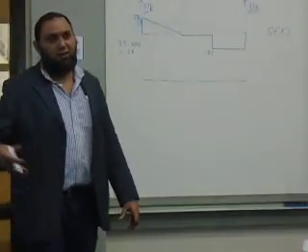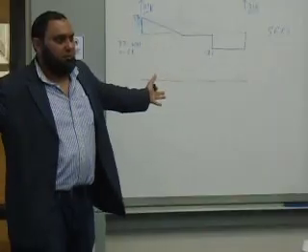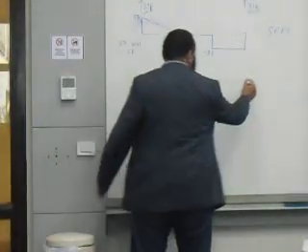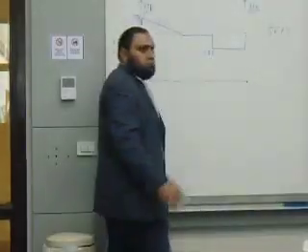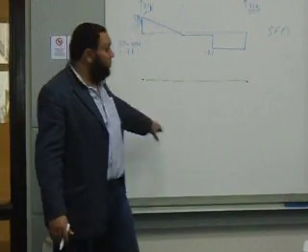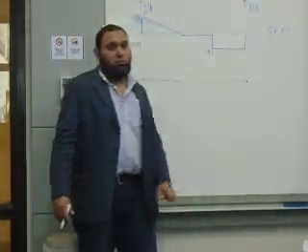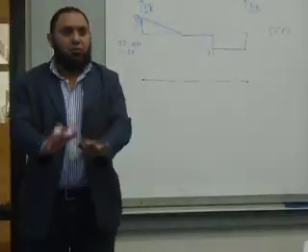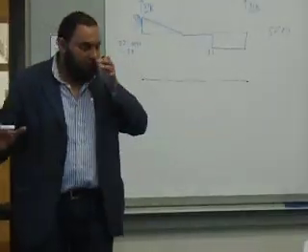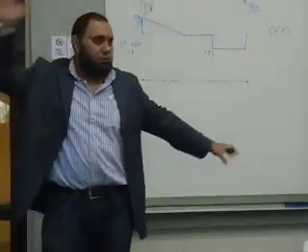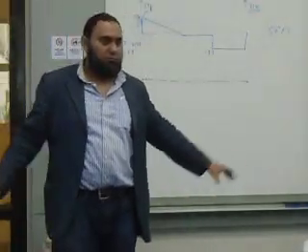And there is just air beside me, right? So these 2 points, I know that they are zeros. That's a 0 and that's a 0, for sure. For sure the bending moment here is 0. For sure the bending moment here is 0. If you give me any other value, that's a conceptual mistake. You're missing a concept. Maybe you thought that this has a fixation. Something is wrong.